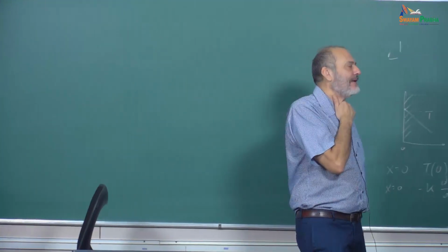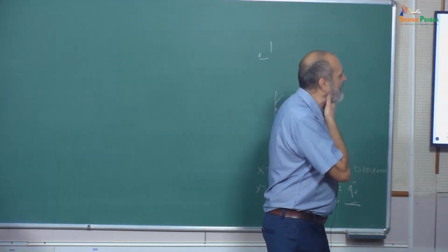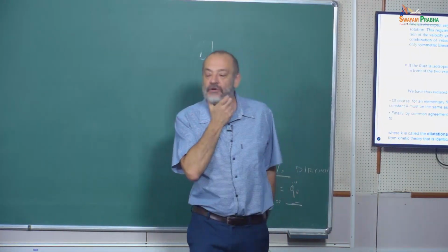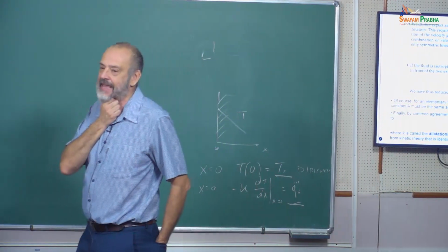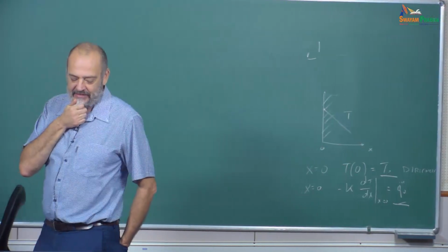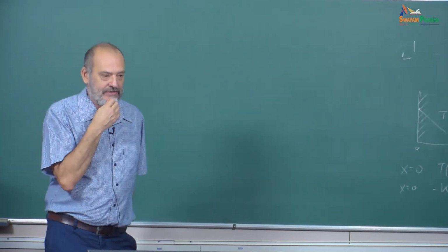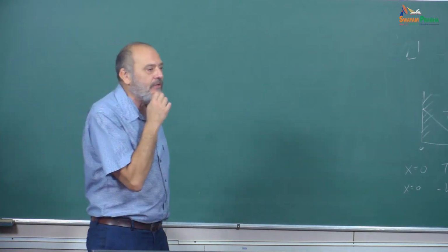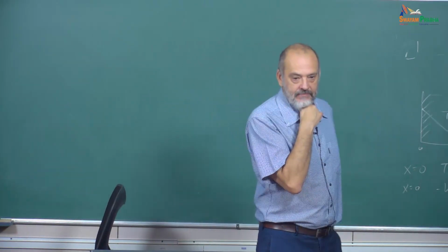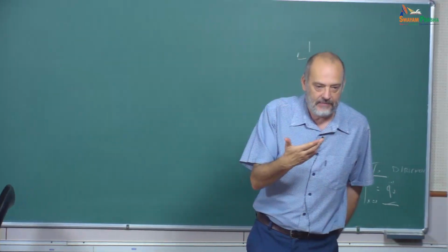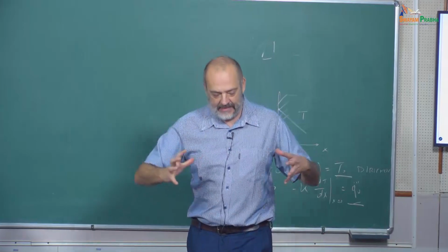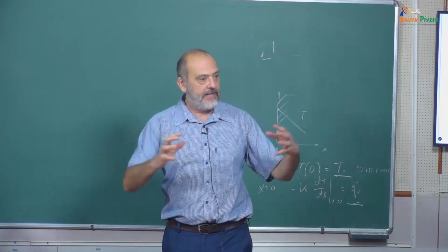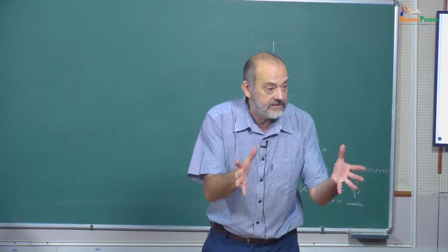Usually what we are using is that B is equal to a third of the dynamic viscosity minus K, and that is called dilatational viscosity, and is used for compressible fluids. So when the fluid is compressible, we think of it as a resistance to compression and dilatation. Okay, this is just that.